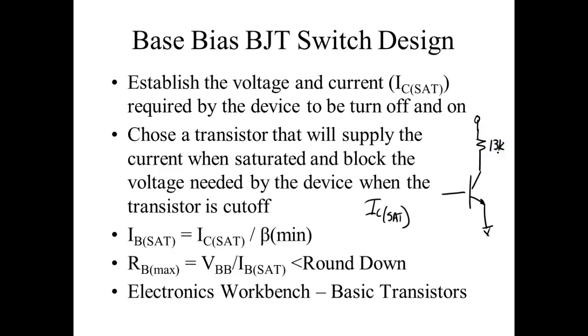What voltage is required by that resistor? This is one thing you're going to have to know: once we move away from a resistor, most loads have a specified voltage. So the voltage I use up here is what's required by the load. What voltage do we want this load to run off of? 5 volts. Okay, so we'll run it off 5 volts.